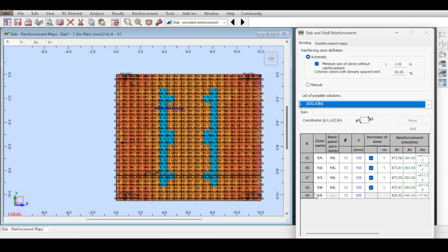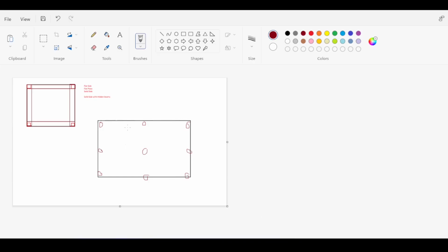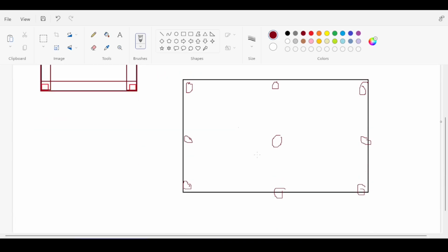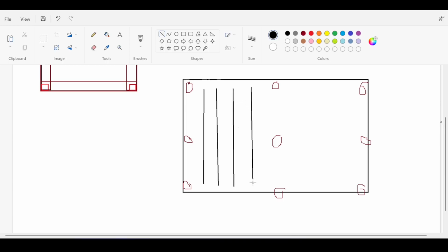1 bar yes, 1 bar no. This is practical. Allow me to explain. Let's say that for the Y, you have not much reinforcement in the middle here. Let's say we are at the top Y now, okay? So you have small reinforcement near the center of the span and larger reinforcement above the places where you have higher moments in Y. If you have two spacings, one of them is exactly double the first one.